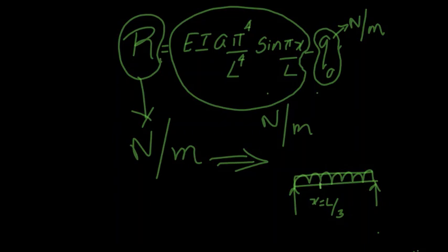If the value of error is 10 right at this point, it means right at this point the rate of loading has an error of 10 Newton per meter, which means if the rate of loading is, let us say, 2 Newtons per meter, then maybe the rate of loading is 12 Newton per meter at the point x is equal to L by 3. This is just an example. Of course, the values are completely erratic, but just an example to get across the concept.